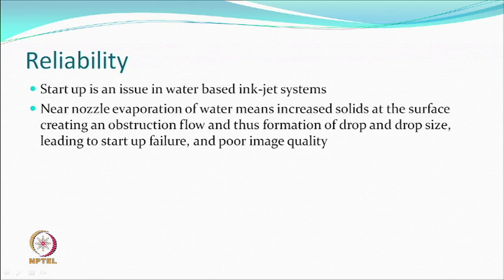And this happens because there is a near nozzle evaporation of water, which means solids at the surfaces are going to be deposited, and so it will cause an obstruction of flow, formation of a drop size, leading to a startup failure, and then of course poor image quality.